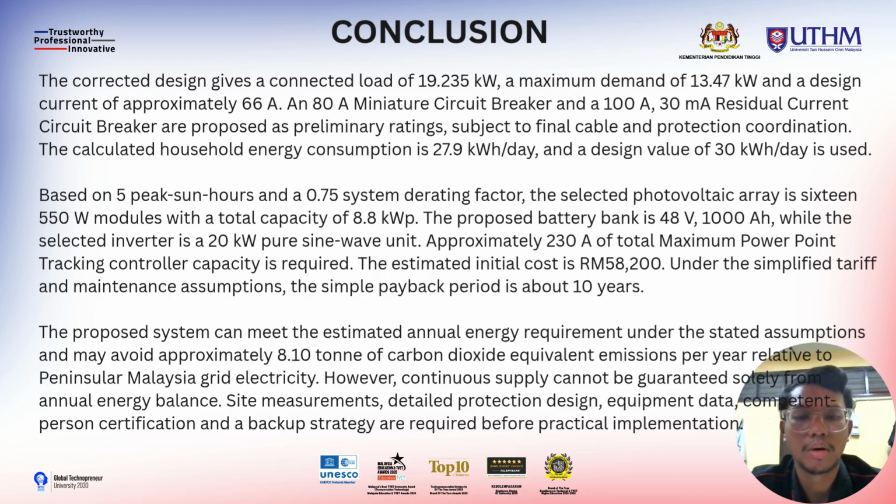The system offers a 10-year simple payback period while mitigating 8.10 tons of CO2 emission annually relative to the Peninsular Malaysia grid. However, because the annual energy balance cannot guarantee an uninterrupted 24/7 power supply, site measurement, detailed production design, a robust backup strategy, and competent person certification are strictly required before physical implementation.